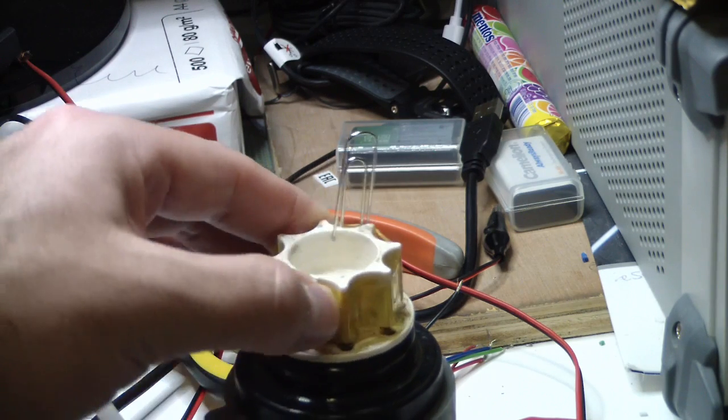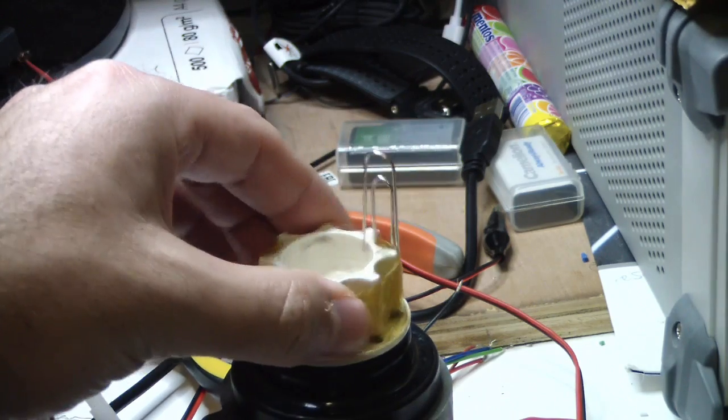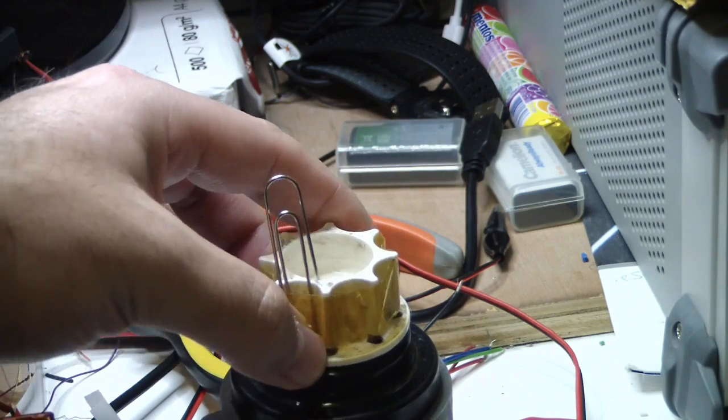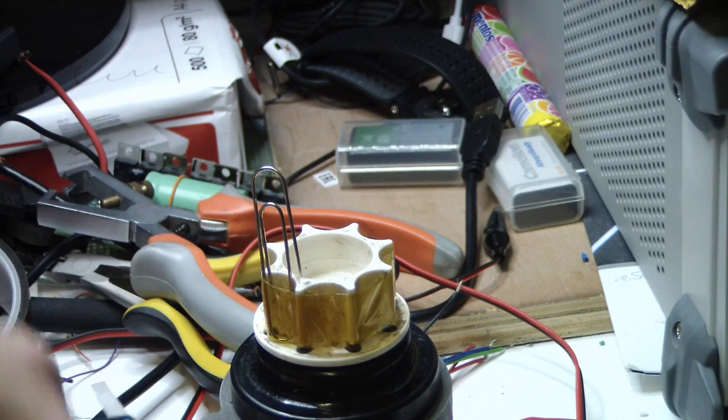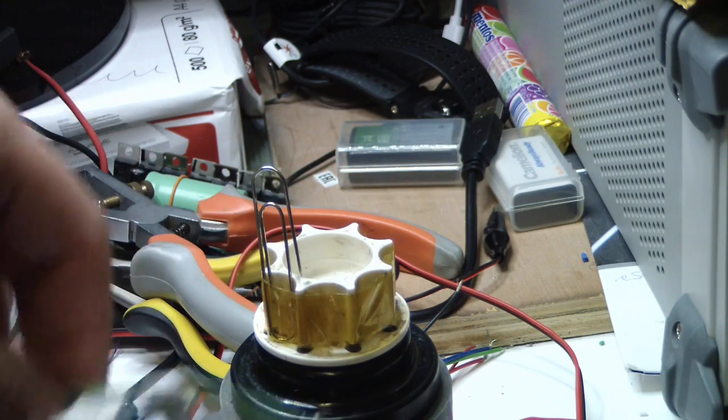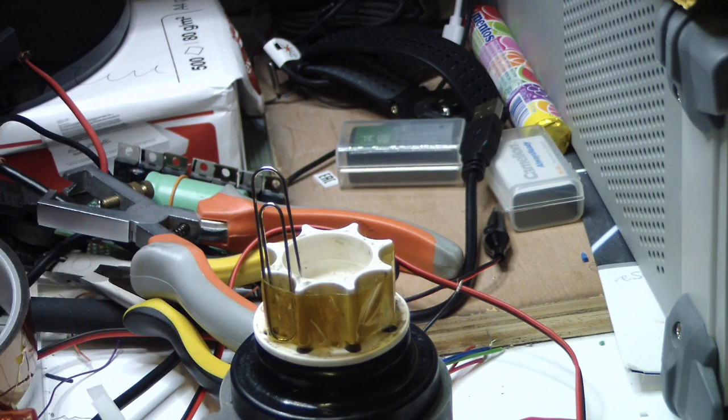Okay, so this is the motor. I have a pin here, and I have this 3 phase here, and I will switch the power into different coils. Each time 2 coils will get something else, and we will see how it is moving. So I start with 1 plus and 3 minus.